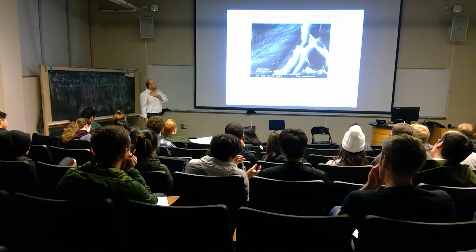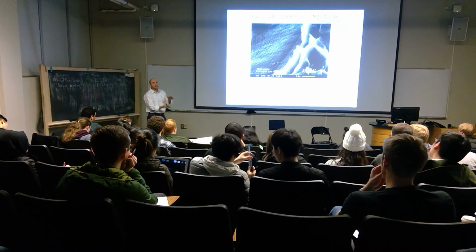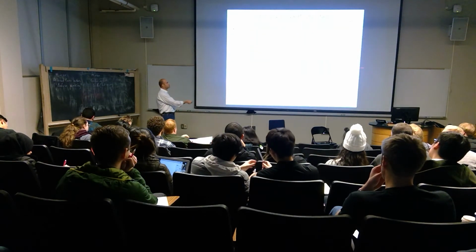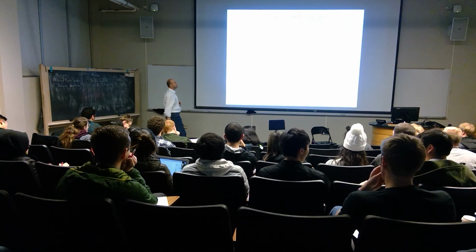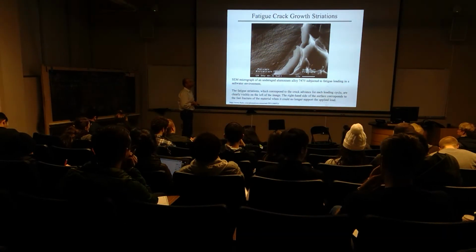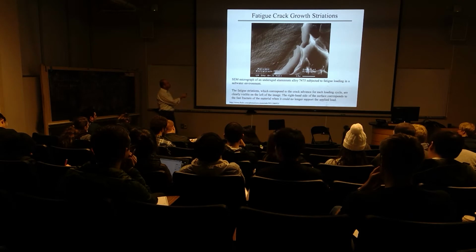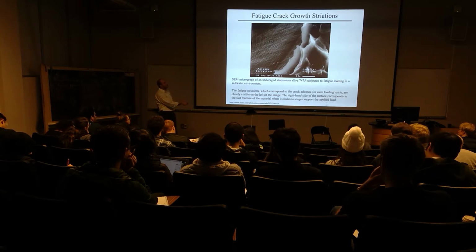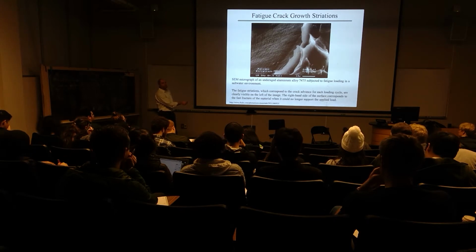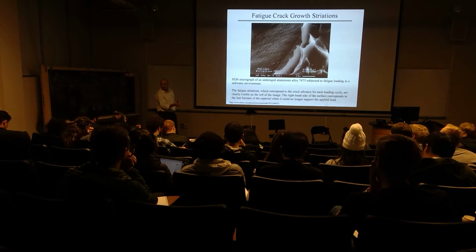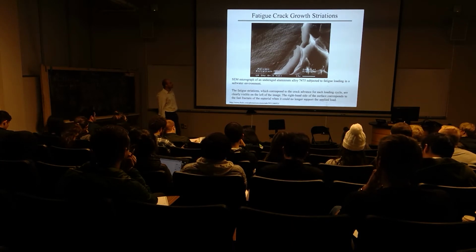But nonetheless, once those cracks start taking off, on that portion of the surface that's right here, you should see the history of that slightly cracked extension. So you'll see striations that will be present on the surface, and they should continue all the way up to the point you reach unstable fracture, and bulk fracture comes through the specimen as a result of linear elastic fracture mechanics. Okay.